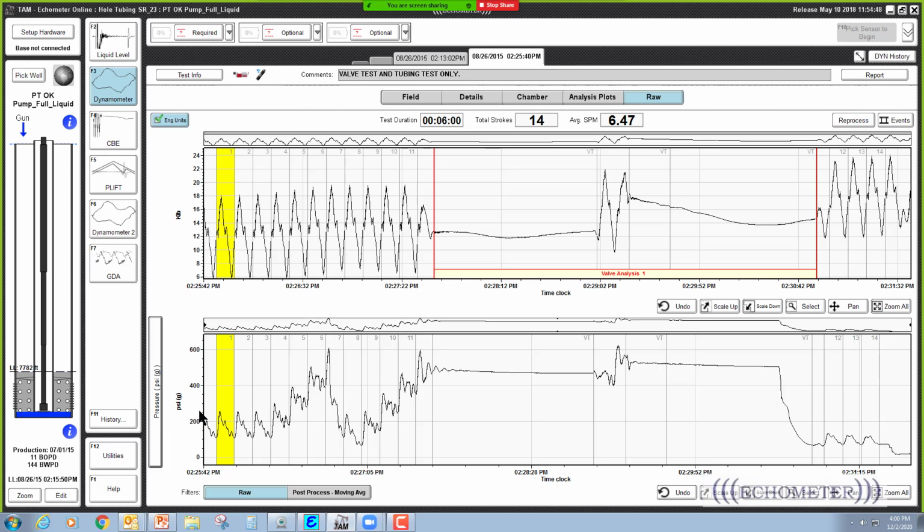We're interested in pressure now. This shows that right here he closed the valve and increased the pressure, and found out that it took 1, 2, 3 strokes to pressure up the tubing. So then he could say, okay, now I know. Joe Norman said, now I know I can walk to the back of the unit, close the T, walk to the back, and in 3 or 4 strokes I need to shut it,